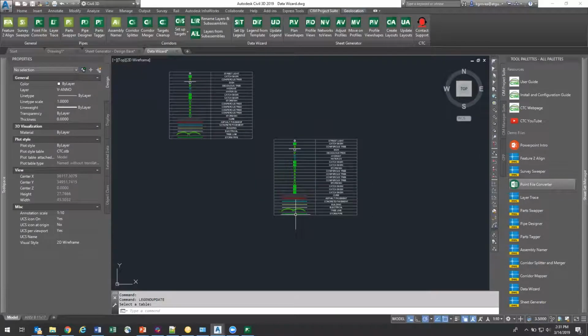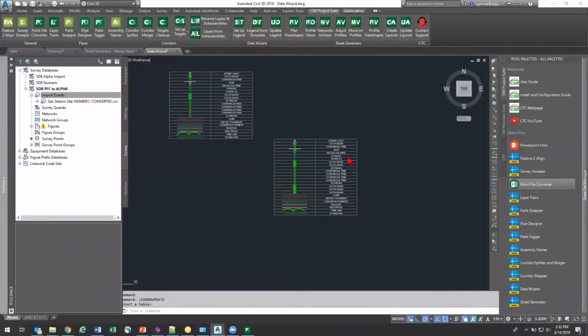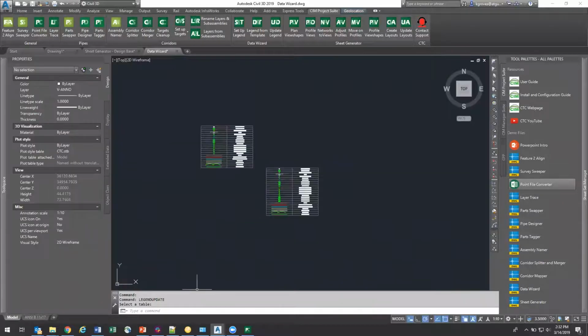So it's super useful for two things. It's going to help us out with our legend creation inside Civil 3D, but it's also going to help us track this information, count it up, and help us with our QTO throughout our project. We do have to press the button every time, but the way that it tracks that information is super dynamic and a lot more intuitive to manipulate than the Civil 3D out-of-the-box QTO manager. So with that, that is our half an hour.